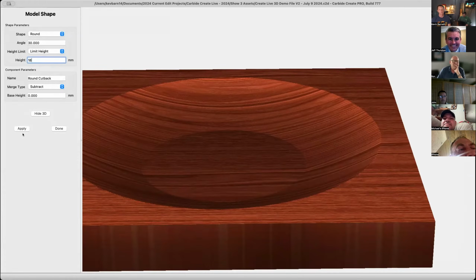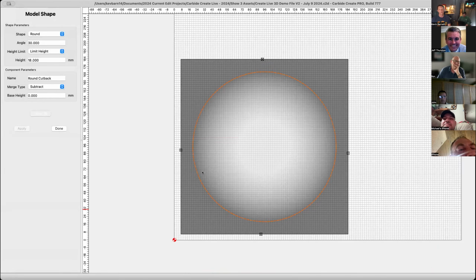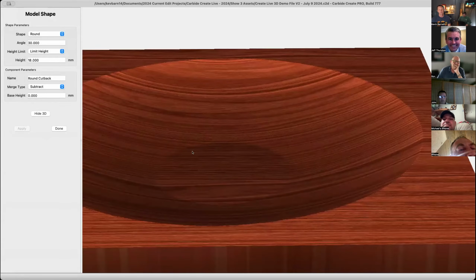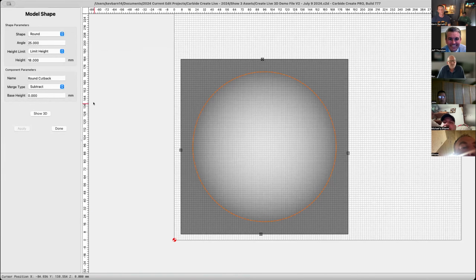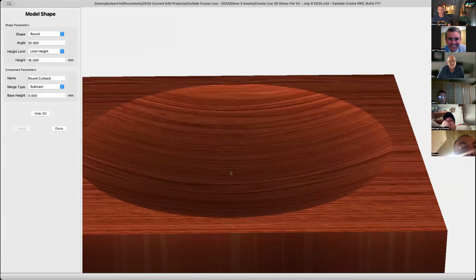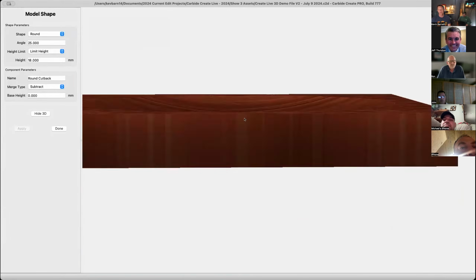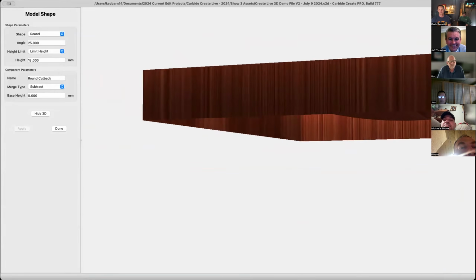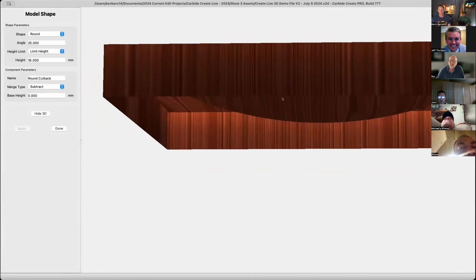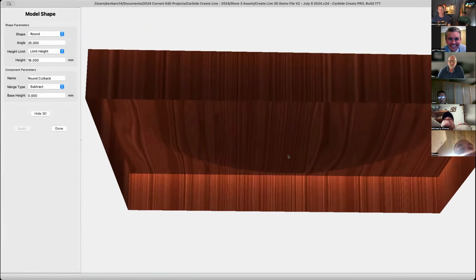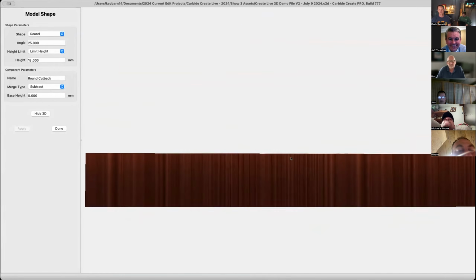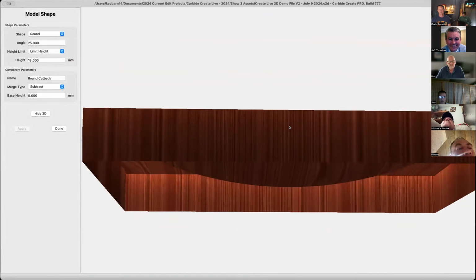What if I want to go to 18 millimeters? Now I'm just going to leave 2 at the bottom, which is probably not enough to sustain it. But there's 2 millimeters. So at 30 degrees, we're pretty close to going through the entirety of our material. We're very close. So I think at 25 degrees is probably better. And we're going to leave some decent amount of material behind this cut. You can come and look at it back here. You can't really measure it per se, but you can look at it on the underneath side of the 3D to give yourself an idea of, are you clearing the thickness of your material?